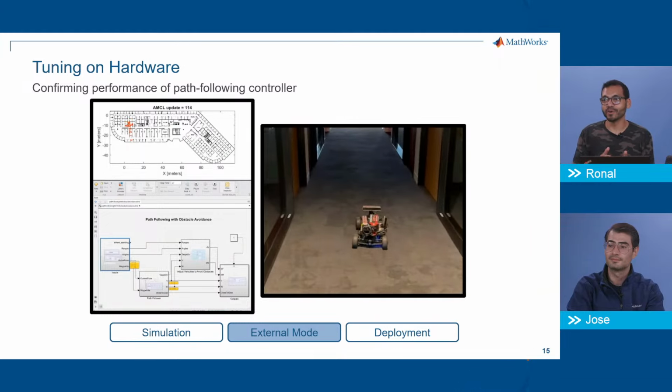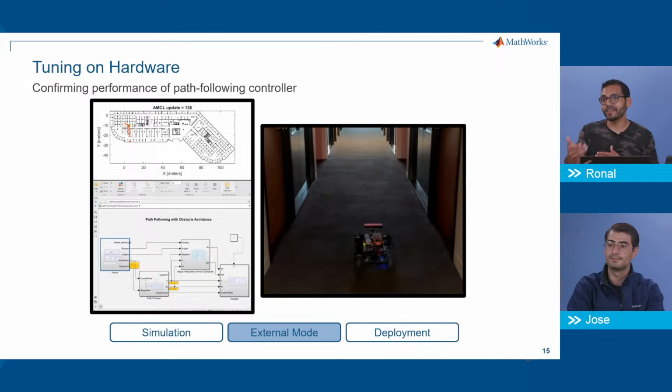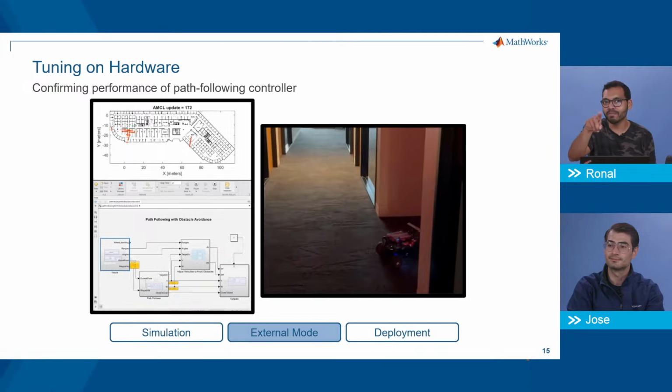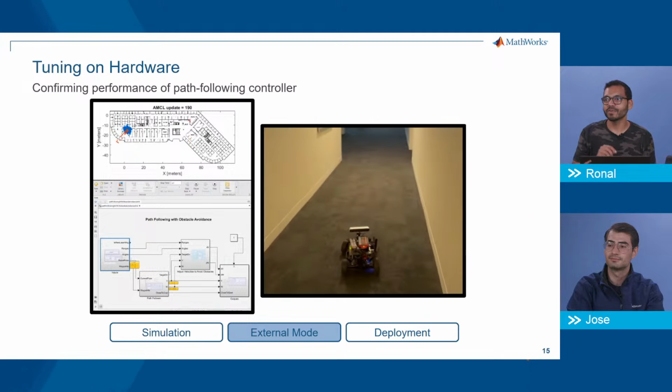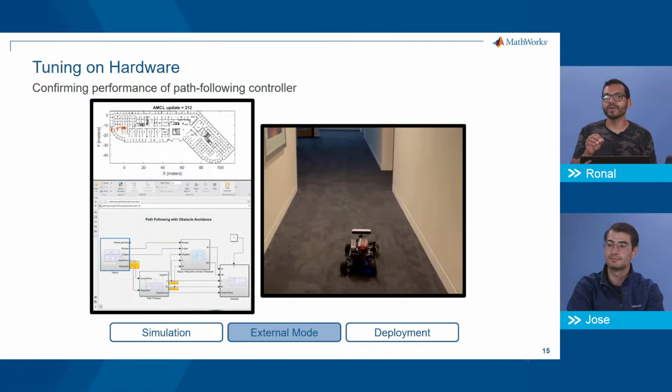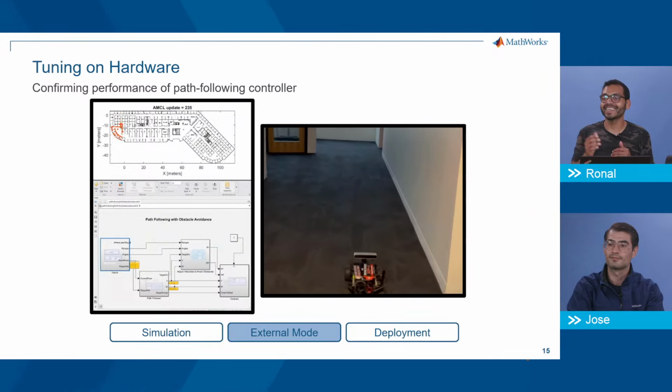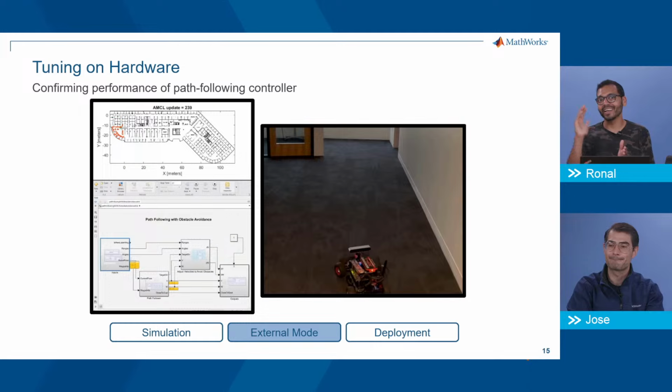If I see that the robot's turning too much to the right or left, I can look at the LiDAR data to see why. So you can notice this robot tends to bounce around in the center when it travels through there. That's because it gets LiDAR data from walls, or sometimes it's just a glass, and it's trying to stay in the center. So when a glass comes, it decides, oh, I need to move closer to this wall because it's a glass.